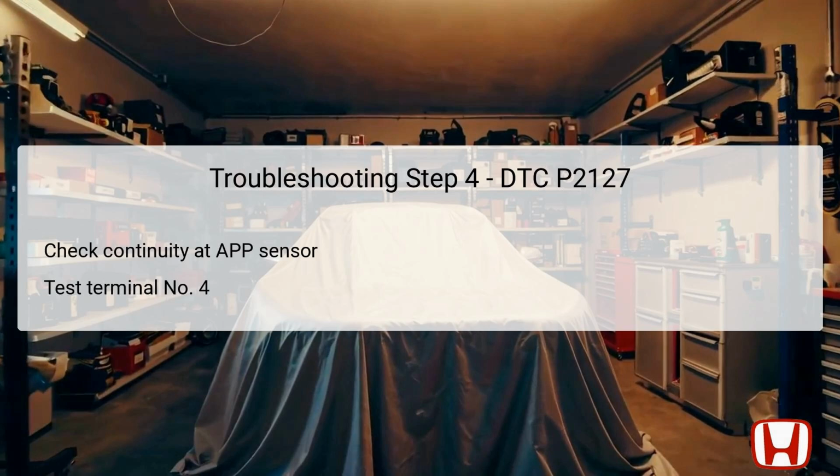Identifying ground issues is essential, as they are a common cause of sensor malfunctions, often leading to the low voltage condition indicated by DTC P2127. Correcting this aspect could resolve the trouble code effectively.